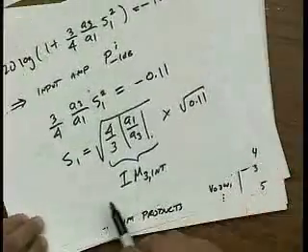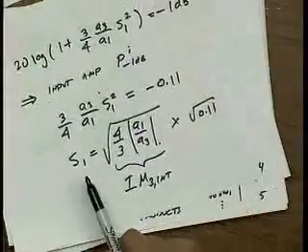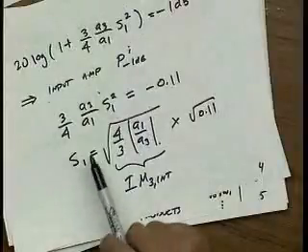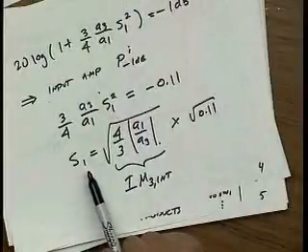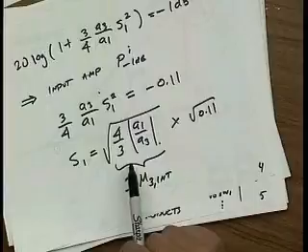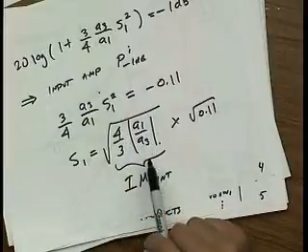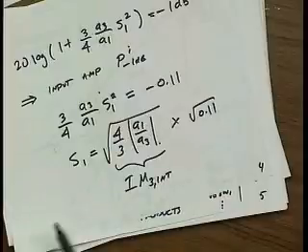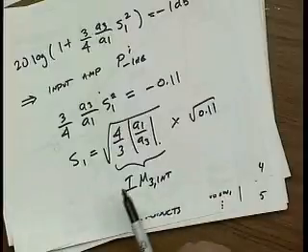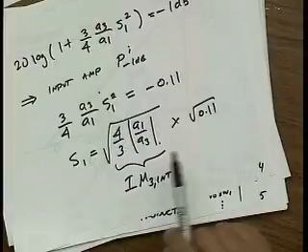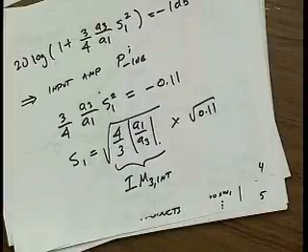Look at the input that I need. What is this input power? This is the input power that corresponds to the gain dropping by 1 dB. It's also the square root of 4/3 A1 over A3. And that's why here I wrote down this is the IM3 intercept point. Okay? So at that point I hadn't introduced it. Didn't want to confuse you guys, so let's go back and look at that.